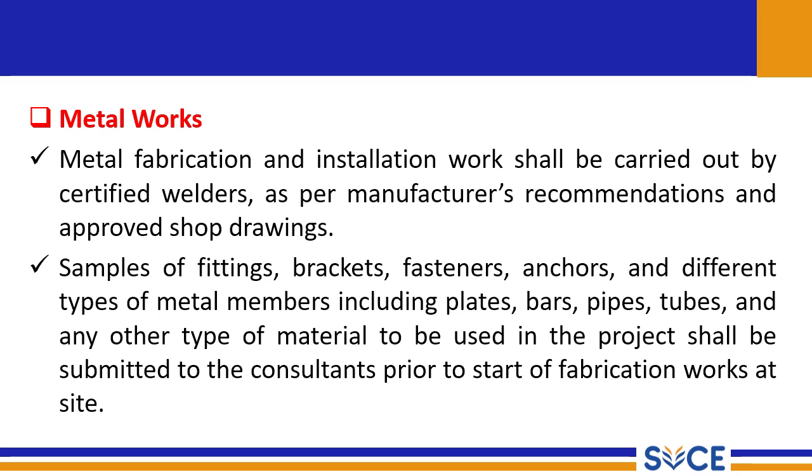Metalworks. Metal fabrication and installation work shall be carried out by certified welders as per manufacturer's recommendations and approved shop drawings. Examples of fittings, brackets, fasteners, anchors, and different types of metal members, including plate, bars, pipes, tubes, and other types of material to be used in the project, shall be submitted to the consultant prior to the start of fabrication works at site.